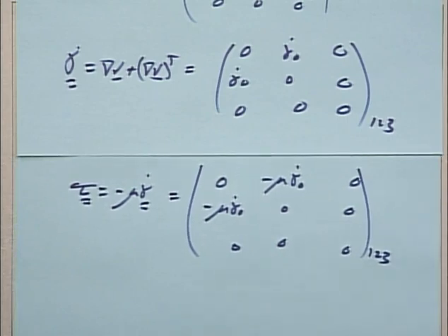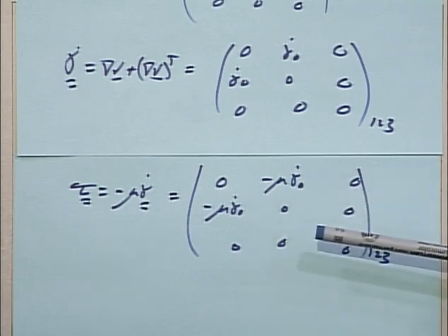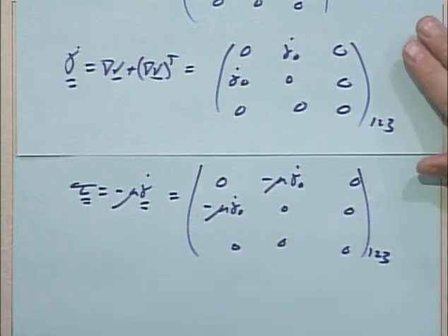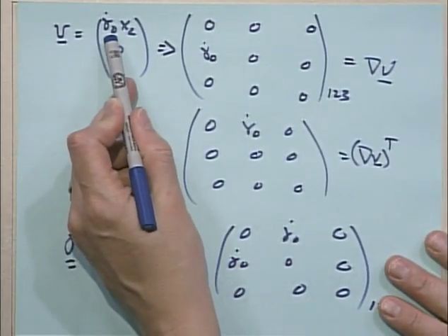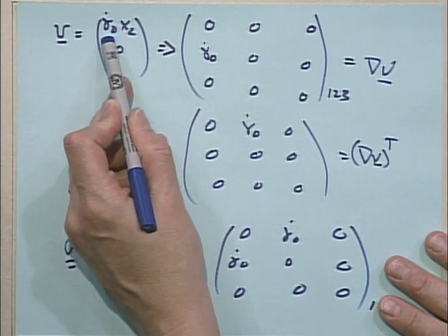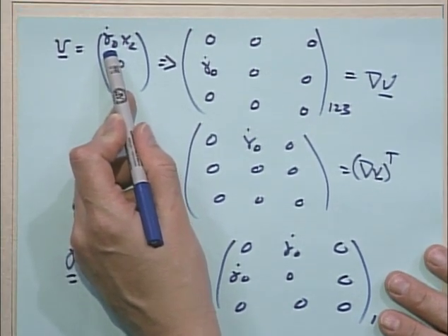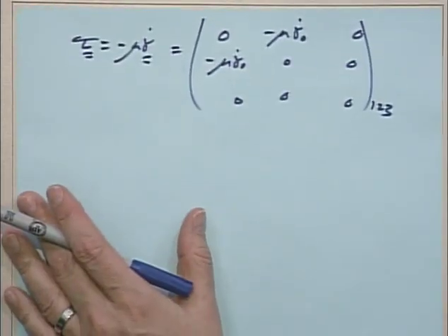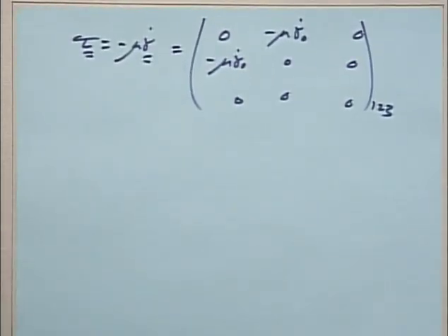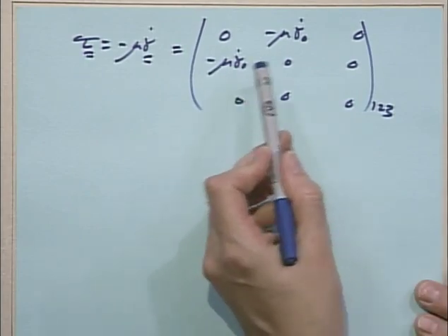So for the flow with this velocity, this is the stress at every point in the fluid. It's independent of time. There was no time in it because back here when we specified the velocity, we put a constant in where the time function appeared. This is the simplest flow, which is steady shear flow. So this is the stress at all times and all places. It's a constant. There's nothing in here that varies.